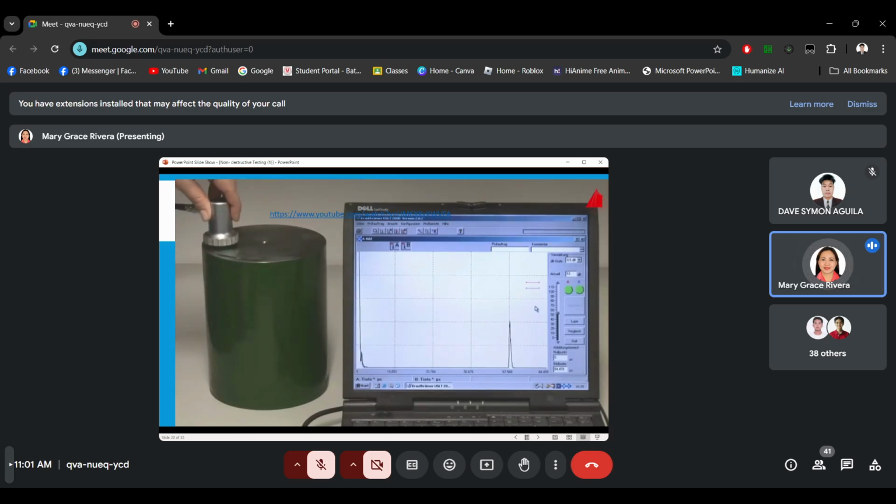Using the velocity of sound in the material, one can plot the calculated depth on the monitor to the right instead of time. A very useful feature. With the help of so-called trigger gates, which may be set on the echoes with a computer mouse, the depth of the defects can easily be read off at the lower left-hand corner of the monitor. The cylinder back wall lies at a depth of about 200 millimeters below the probe, so the cylinder has a height of 200 millimeters. And here we go. The material tester scans the upper front end of the cylinder with the probe and observes the monitor. A defect echo appears on the monitor. This defect is located in a depth of 130 millimeters below the surface.